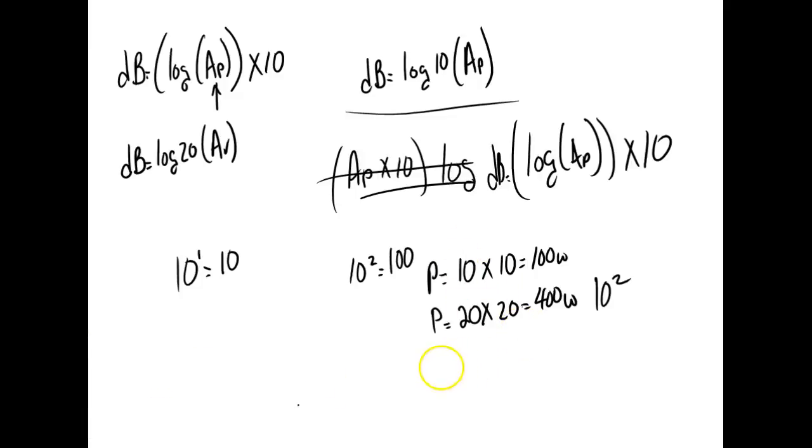If I raise my voltage up to 7.07 volts, my current's going to go to 7.07, and my power would go up to what? Yeah, 50 watts. Y'all understand, 7.07 is a round number. It's actually the reciprocal of the square root of 2. Square root of 2 is 1.4142. So if you were to do that for 0.707, it'd be perfect. We can't measure that fraction anyway, so 70.7% would be fine.